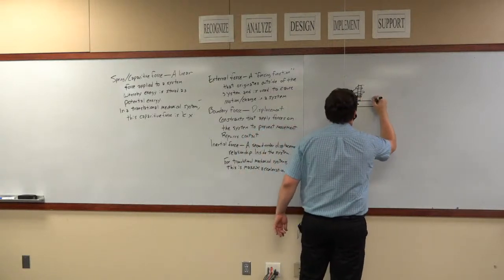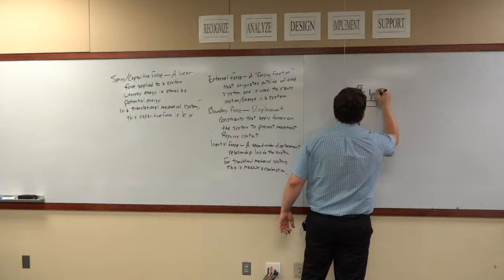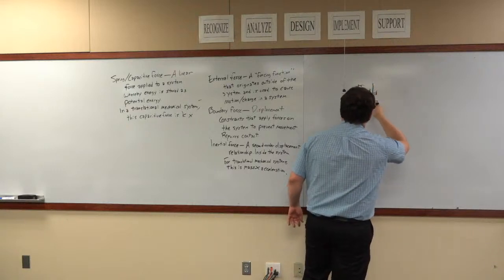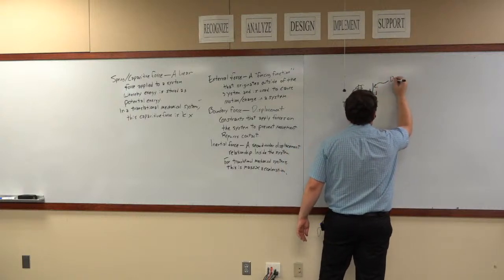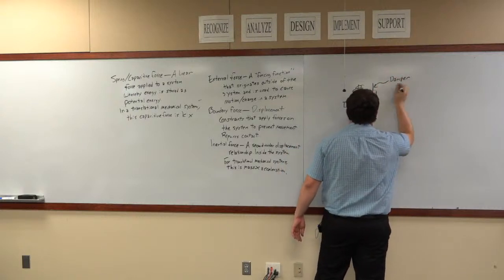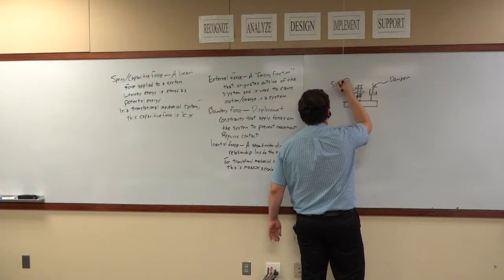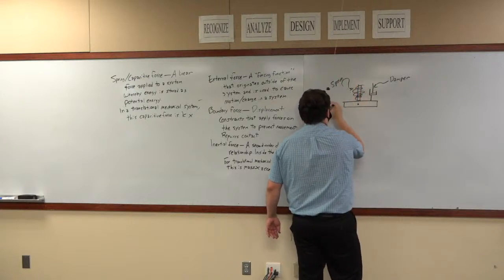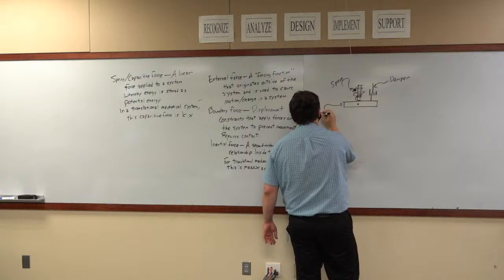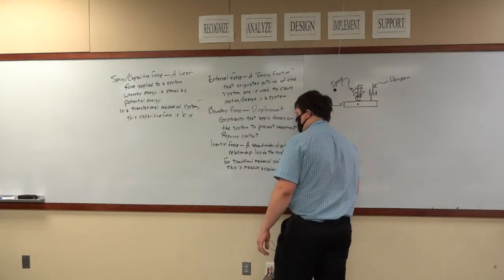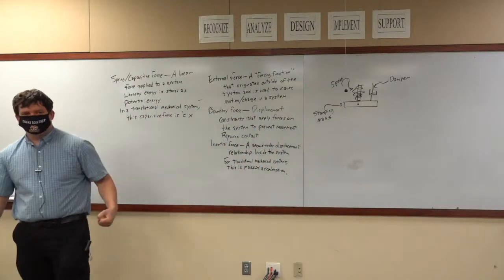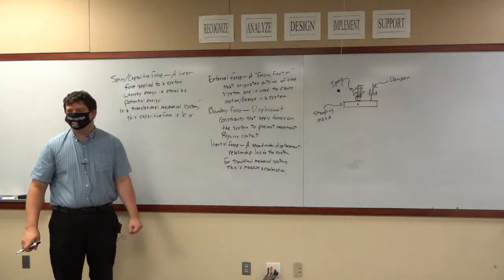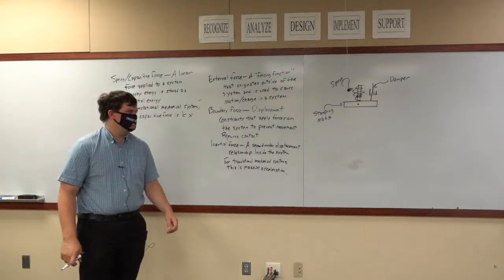And then what we're going to do is we're also going to apply some kind of a damper. Okay? And this is a damper. This is a spring. And this is a stamping mass. Okay, because again, we're just dealing with some kind of a mechanical stamper that comes down, smashes into a piece of metal, pulls back up. Okay?